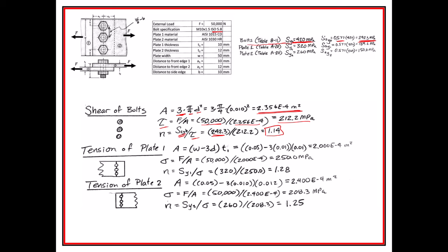And this is a big time apples to apples thing, right? We would talk about apples to apples. Oh man, this is definitely the apples to apples of all time, because we really want to be able to get the correct area for the loading condition. We want to put on the correct load too in some cases. So we find out the right kind of stress, and then we figure out the right kind of strength for the material. So they have to match up so that we get a ratio, and we could judge what the safety factor is.